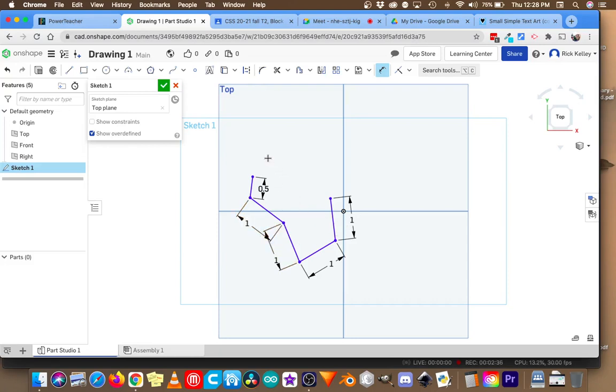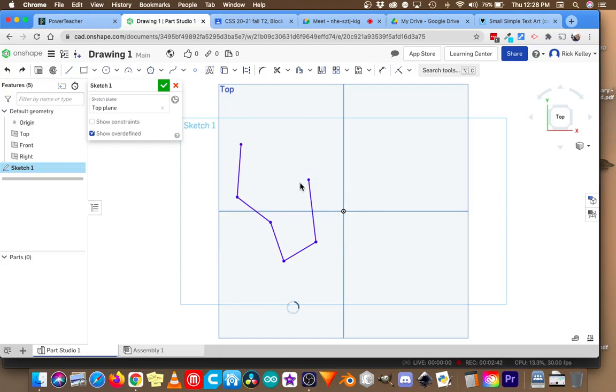So what I'm going to do is I'm just going to undo all of this and show you a better way to do this. Your drawings really should have a plan from the start. So if I start that line tool again and put in a couple of points, right there it gives me a number. That number will go in as a hard dimension if I just press enter. So boom, there it is. Now that object is something that I can work with later.